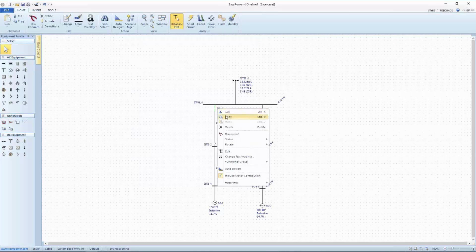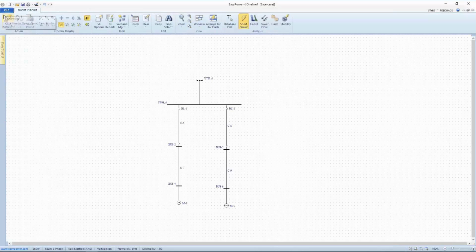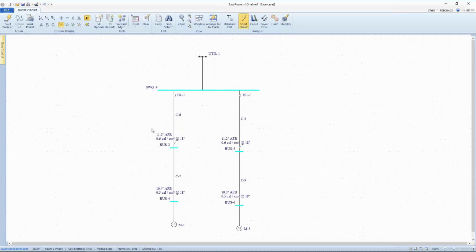Now I know at the time I said that the breakers for the lumped loads weren't that critical, and they're not in terms of what these calculations are, but it gives us the ability to go through and make some characterizations of what is going to be downstream, and we see that this is fairly benign in terms of arc flash. So this gives me the ability to put at least a label with accurate or somewhat accurate information on here to make sure that operators know when they open up these safety switches that they have the potential arc flash PPE required.